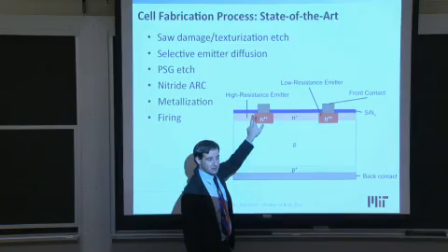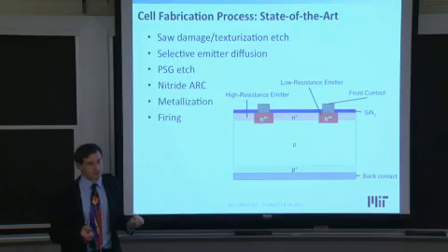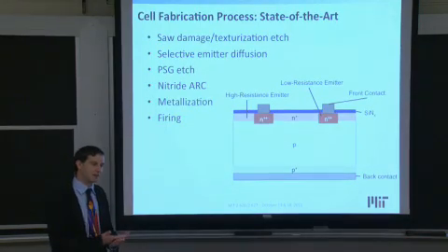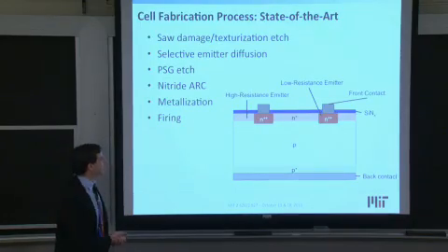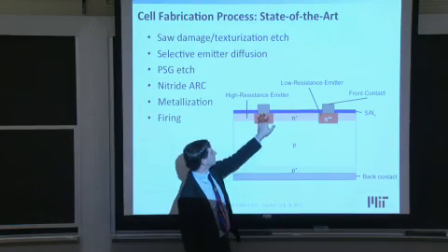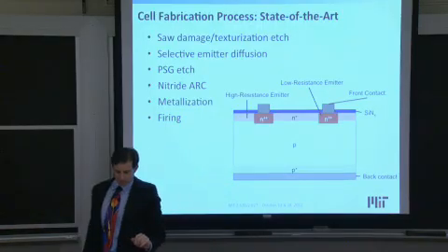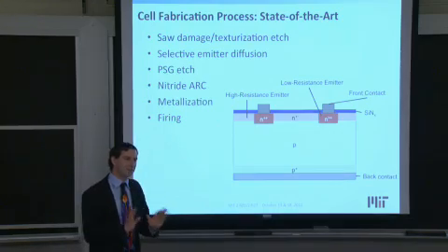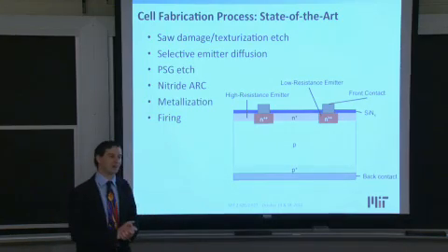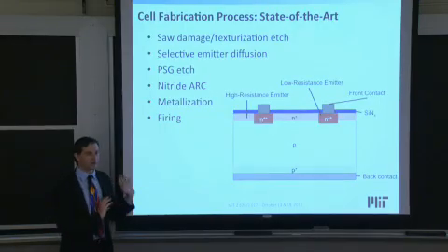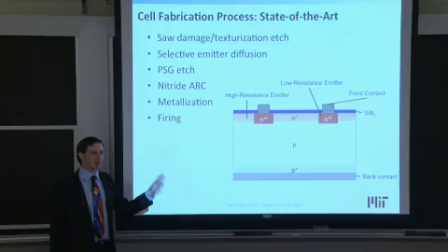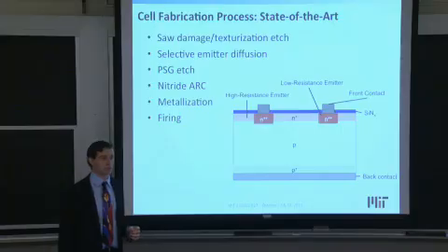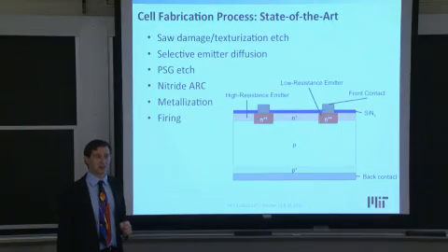This is only 70 nanometers thick, but silicon nitride is a very strong material. It's a ceramic material, so you have to be able to etch through the silicon nitride and make electrical contact with the silicon underneath. And some of the earliest screen printed metallization cells that got in the range of 15 or 16% efficiency only made electrical contact in about 10% of the silicon. But it was enough to have these percolation paths for current to flow up into the metallization. It's a miracle that it works at all. But it's a very effective, cheap manufacturing process that nevertheless is still being used in commercial production today, even among some of the highest efficiency cell architectures.